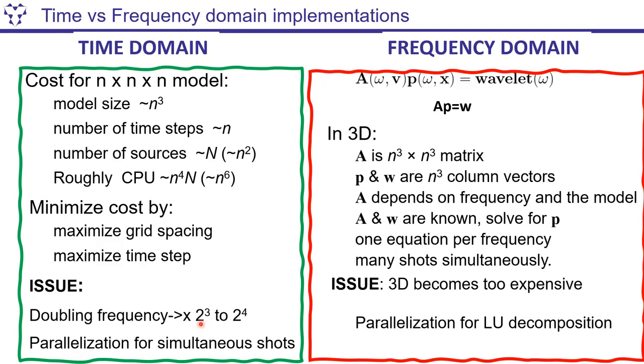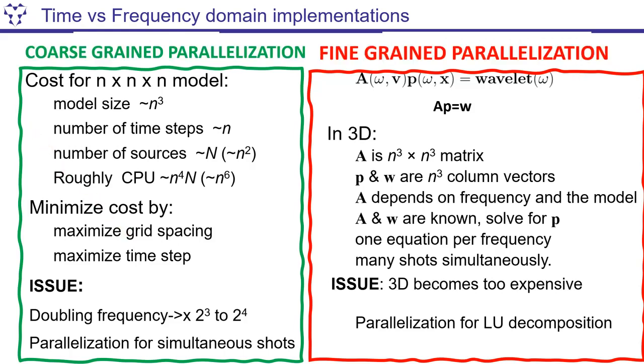And this will be very important as we go to higher frequencies, because finite difference requires finer grids to achieve higher frequencies, and therefore the number of cells along each dimension has to double every time you double the frequency. Right? So we will see that this is the fundamental reason why the computational cost grows very high as we go to very high frequencies.